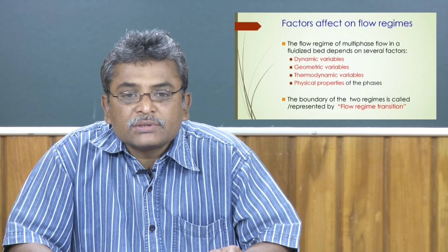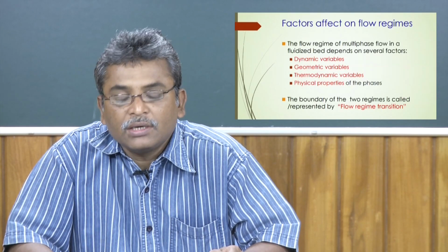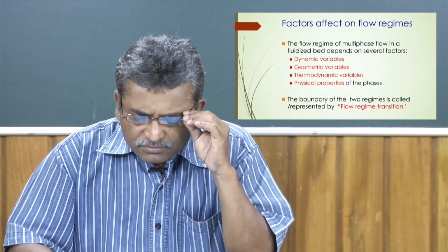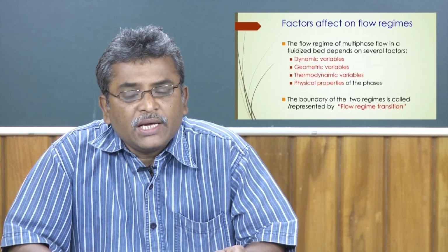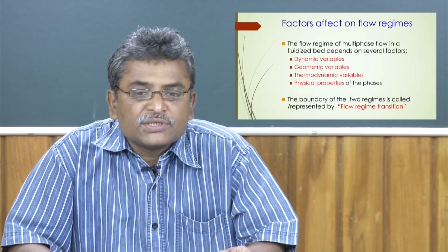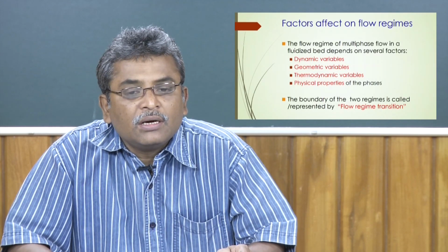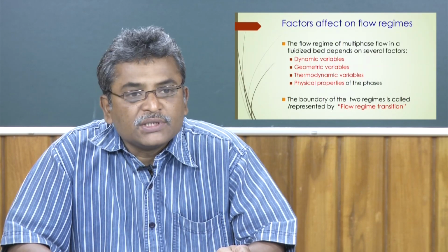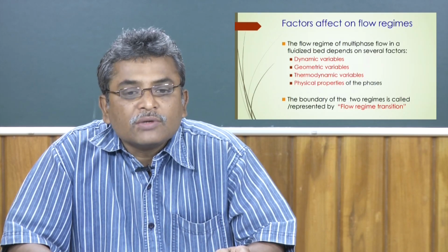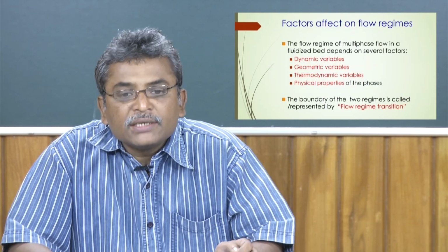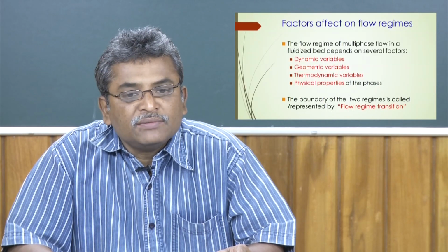Physical properties, of course, in any fluidized bed, whether it is gas solid or gas liquid and solid multiphase fluidized system, the physical properties like density, surface tension and viscosity of the fluid medium will affect the fluidization characteristics, like flow regimes. If you change the properties of the fluid and also other dynamic, geometric and thermodynamic variables, then you will of course have different types of flow regimes inside the bed.